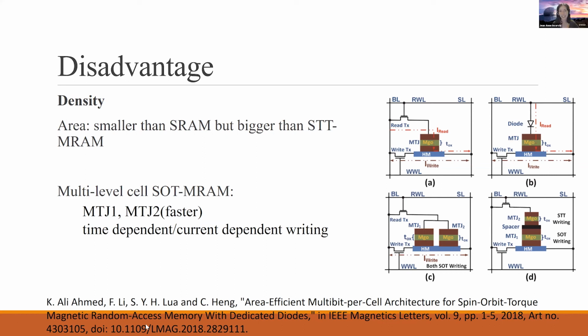If I was to guess, B was them considering the diode as a selector. So instead of having a 2T, you have a selector and a 1T. I know Samir knew this, but for everyone else, a lot of things like RAM use selectors so that they can get away with not having a transistor resistor structure, which is a huge area overhead.